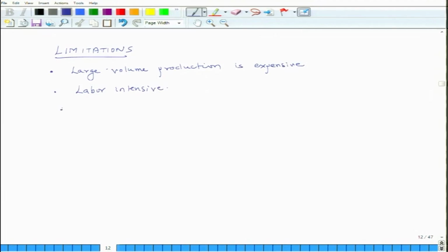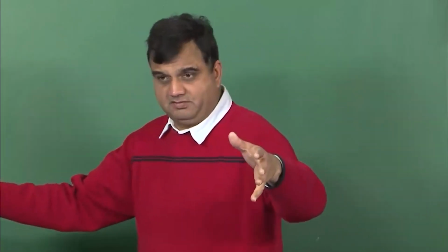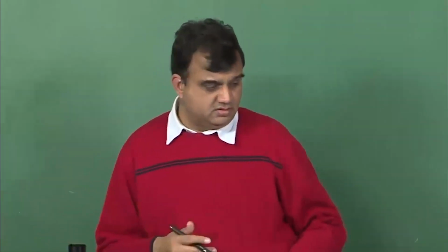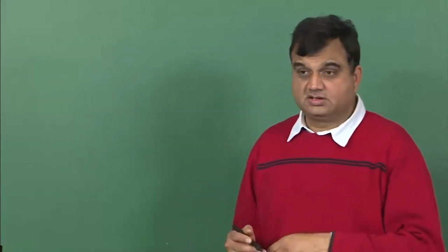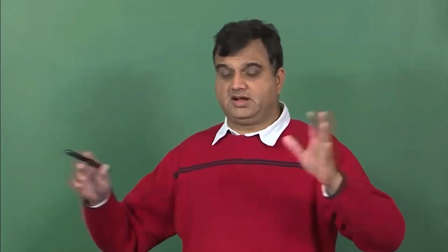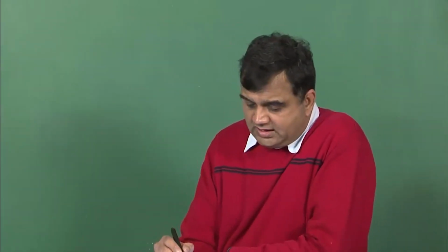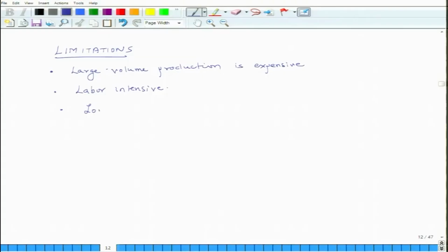Typically, suppose you are making a large part, you cannot put that whole mold in a big oven and heat it very easily. Okay? So, what that means is that you leave it at room temperature and let it cure slowly, and what that implies is that the cure time is long, and if it is long cure time, again you cannot produce very large number of parts in short period.